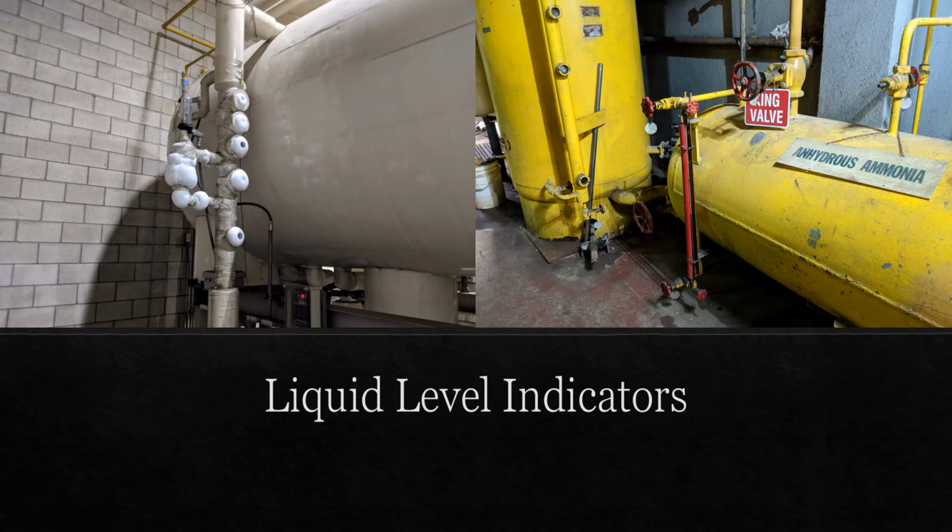Section 7.4 concludes by addressing visual level indicators. First, sight glasses must not be installed where risk of hydraulic shock exists. Second, all level indicators must be protected from physical damage. Third, with the exception of a bullseye column, linear level indicators must be fitted with internal check-type shutoff valves and have protection against accidental breakage of the glass tube from any direction. And finally, when bullseye sight glasses are used, they must be compatible with ammonia and sized for the intended application.